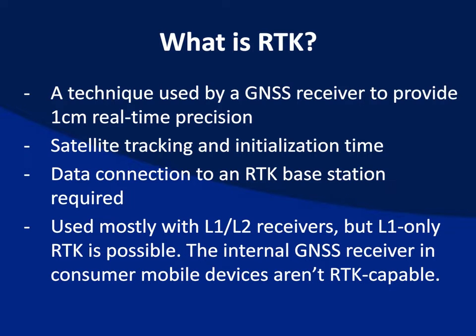So RTK takes some amount of initialization time. When you first turn it on, it's got to resolve ambiguities, and I won't get into that much, but basically it's initialization time that takes time in order to get to that 1 centimeter positioning. And the reason I say satellite tracking in there is because the more satellites the better for RTK, and really you want a minimum of 6 satellites that you're tracking.